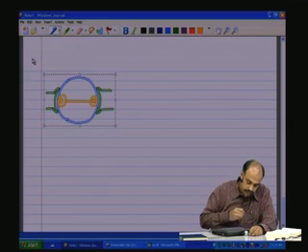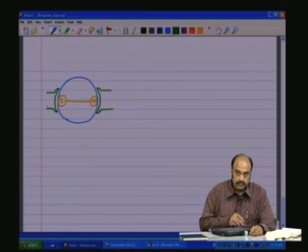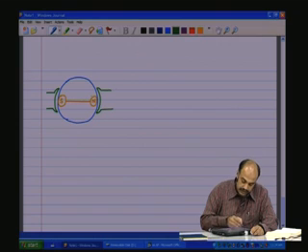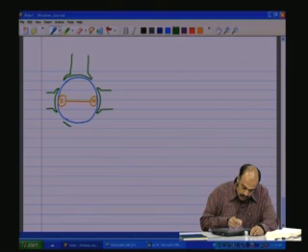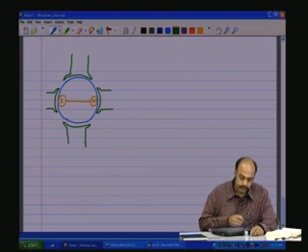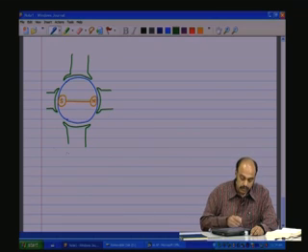Let me have this figure. So here we have just one pole pair or two poles. Here P is equal to 2. Now let me have two more poles in the A phase, all A phase, and the windings are done such that the north and south poles alternate.